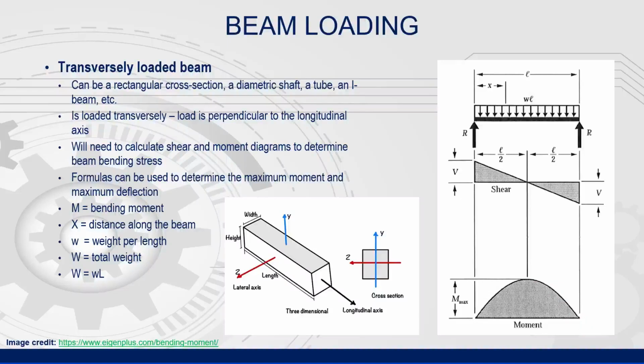For moment diagrams, clockwise moments are considered positive. And remember, this is opposite from the way we normally treat moments in equilibrium equations, where counterclockwise is positive.